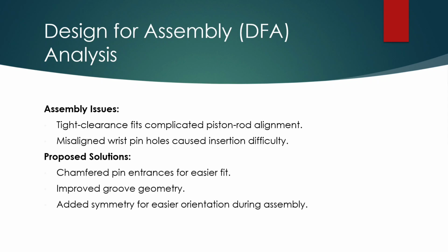So our solution is very simple. We want a chamfered pin entrance for easier fit. We improved the groove geometry, by which we have the access to move the machine here and there to make sure that the holes and everything, the pistons and rod, can be connected perfectly, so that the synchronization rhythm can be there very effectively during the assembly.